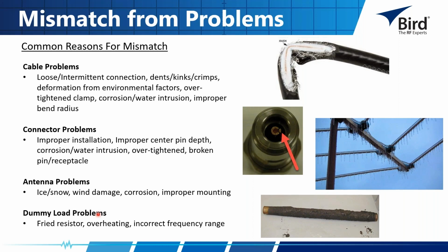And then even things like for a dummy load, a lot of you guys that are performing your calibration over time, the carbon on the surface of the resistor that's internal to these can start to get a little funky. You'll see it in the oil, inside of something like an oil dummy load, where the chemicals are actually being released due to the thermal effects.